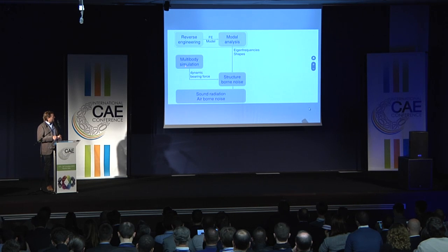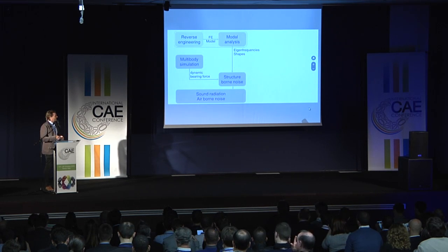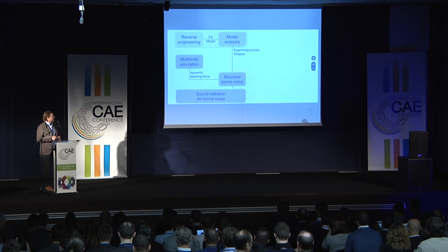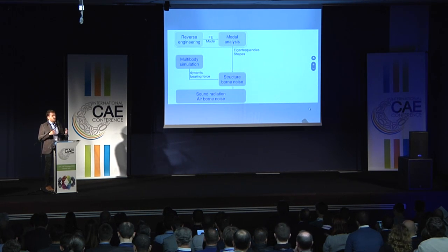The second step is a multi-body simulation, where we calculate dynamic bearing forces, which are the excitation of the gearbox. The structure-borne noise step uses the eigenfrequencies and shapes and the excitation as bearing forces to calculate the velocities of your structure surface.